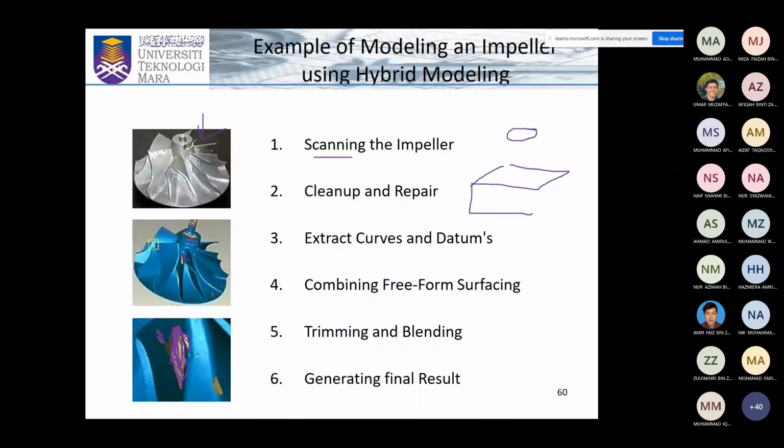Then I say draw a cylinder up to here. What you would do is select a surface over here, let's say there's a plane, and when you extrude, you would extrude all the way in. So it will actually penetrate through your solid. Similarly, we extrude past this boundary. Once we are done with that, we trim any excess, and then we get a clean covered shape.